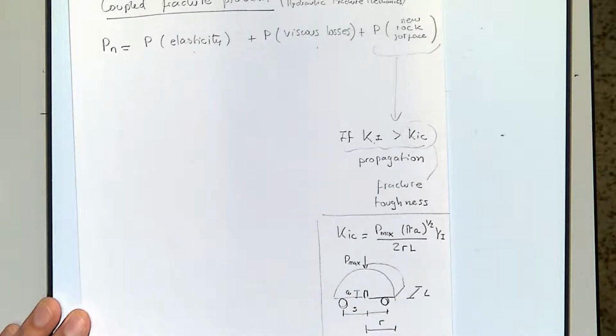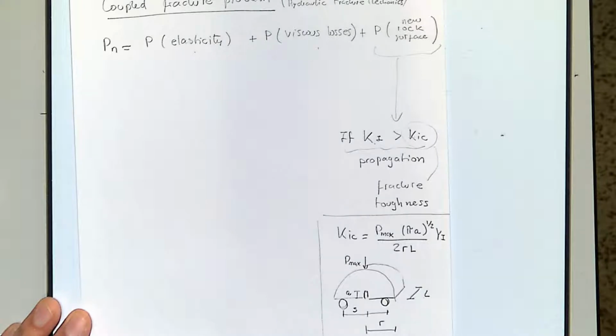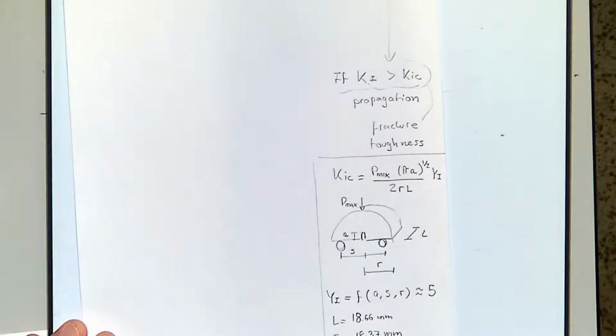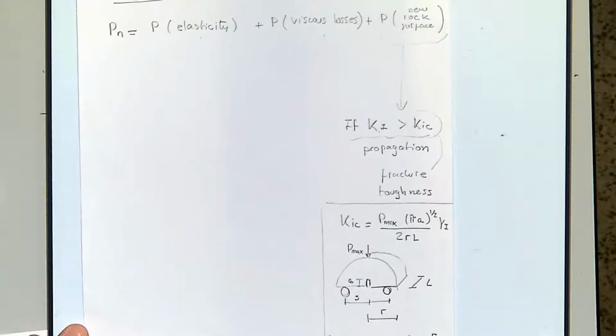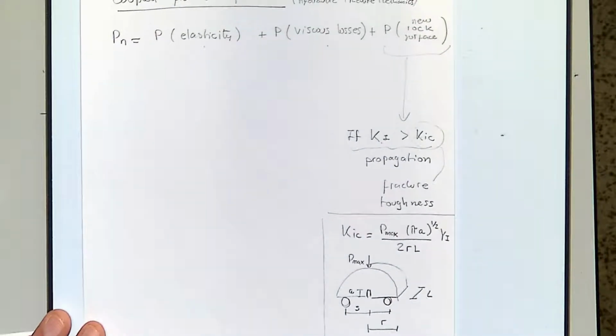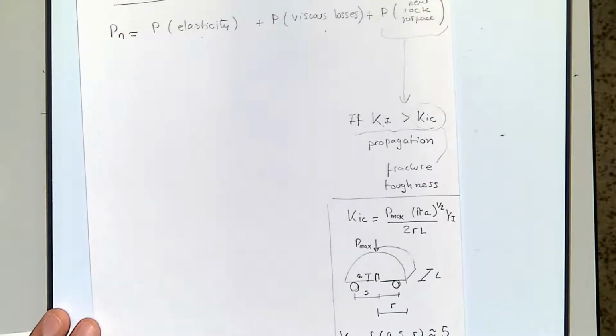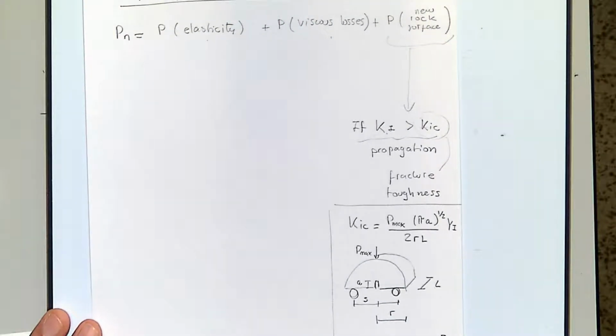For the experiment that we ran in class? No one? Okay, I'm going to give you a few minutes a little bit later, not right now. But you're going to find that these values of toughness vary around 0.1 and 1.5 MPa square root of meter, more or less, for rocks.